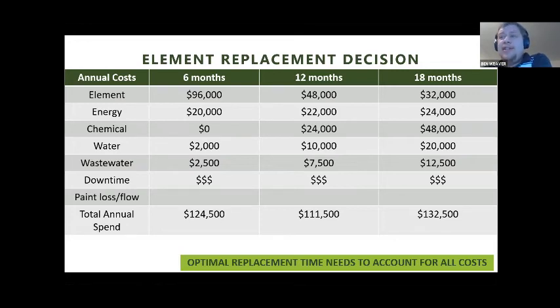And in addition to this, it provides a benefit that we can be a little bit more proactive in making replacement decisions. A lot of the times I see plants where the 8-inch element has dropped below 1 gallon per minute, and it's time to replace. Well, that's the conventional, typical way of thinking, but that's being a little bit reactive. And if you don't have the element on the shelf, how much impact does the lead time of getting the elements to site have?